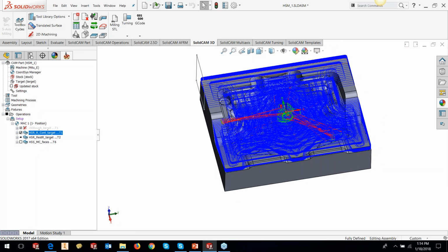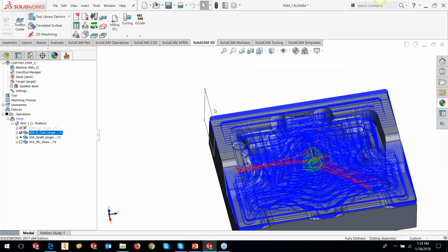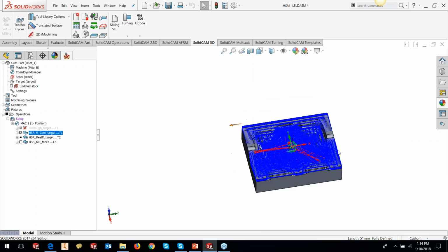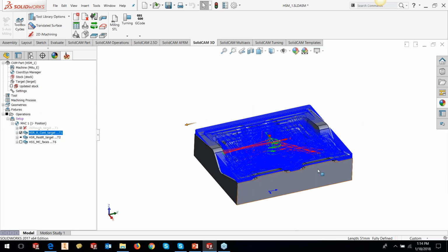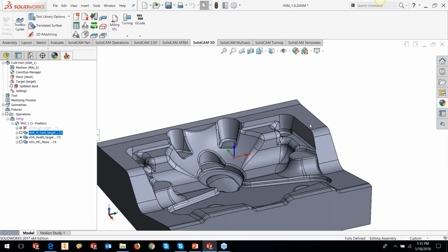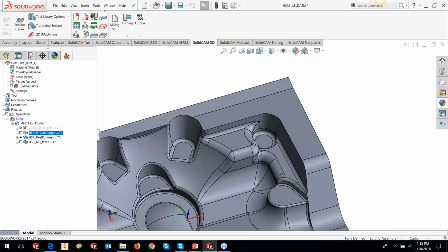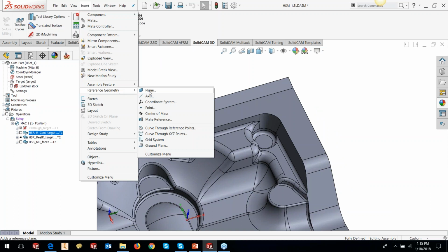Now, like I said, you could edit a toolpath based on simple sketches, and the sketch could be in just any plane. To understand any plane, let's do a simple example. Last time I just took the standard XZ and YZ planes. Let's not take the standard XZ YZ plane. What I'm going to do is make an arbitrary plane.